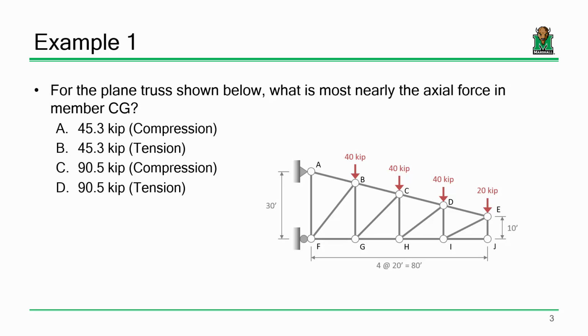Okay, so that's one thing I want you to take away from this session. This is a nasty truss. All the members are at different slope ratios and whatnot, but now looking at it, it's just cut a section, take some moments, and you're done. Okay, so I want you to think in those terms, going with that strategy. All right? Everybody good? I'll tell you what, let's do that. Let's cut a section and take some moments. Let's see what happens.